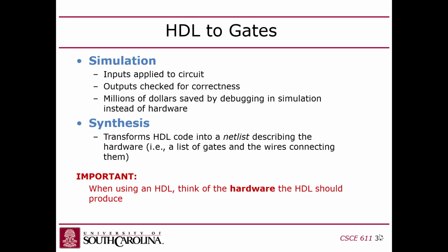Okay, so I mentioned we've got simulation and synthesis. These are two parallel roads that you take from a design. You write something in Verilog, and then you either go down the path of simulation, which is essentially where you're testing your design to see if it works. It's for debugging. And then there's synthesis, where you put it in the hardware.